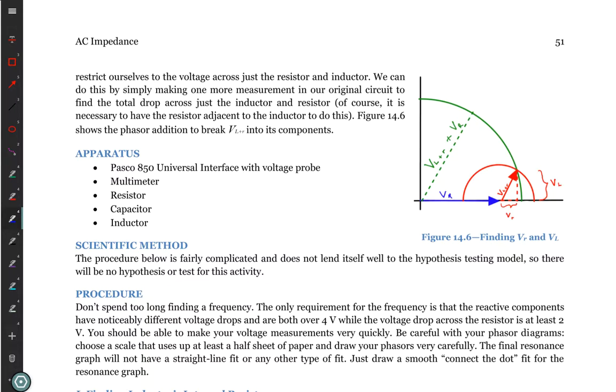And then finally, we have the voltage of those 2 combined. The last number we had, which once again cheating here, was 12.62. That was the voltage of the 2 combined. So then I readjust this so it's 12.62 volts, and I draw the quarter circle that goes from the origin out to that distance.